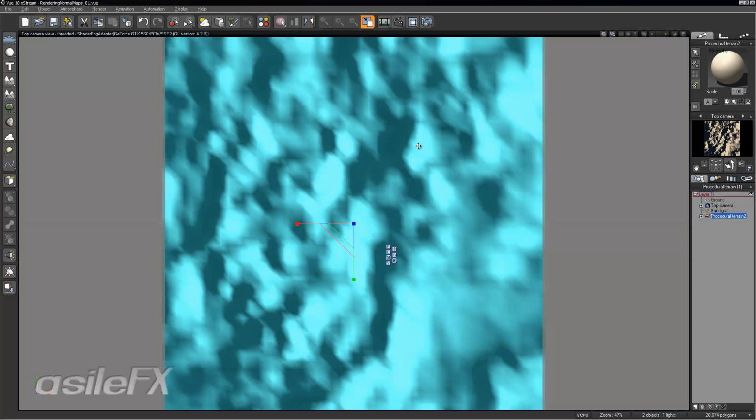Before we go ahead and render, there are a couple of things we need to take into consideration, and also a few modifications that need to be made. First thing is that the multipass outputs aren't typically anti-aliased, at least if you're running through the Xstream plugin, rendering through a host application. So it is a good idea to do this in the standalone application, where the multipass should be anti-aliased.